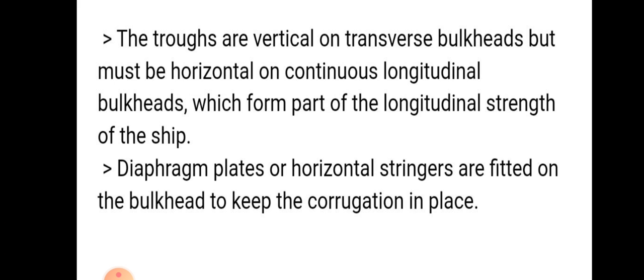The troughs are vertical on a transverse bulkhead, but must be horizontal on a continuous longitudinal bulkhead. This forms part of the longitudinal strength of the ship. And the diaphragm plates or horizontal ridges are fitted on the bulkhead to keep the corrugation in place.